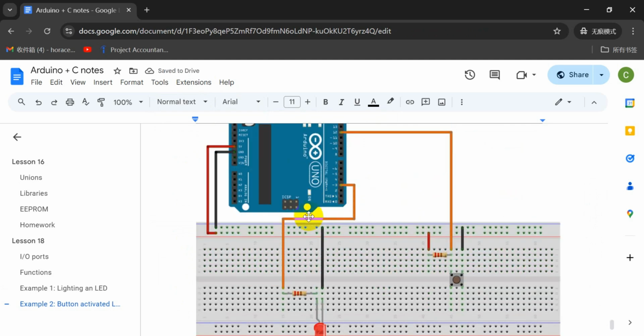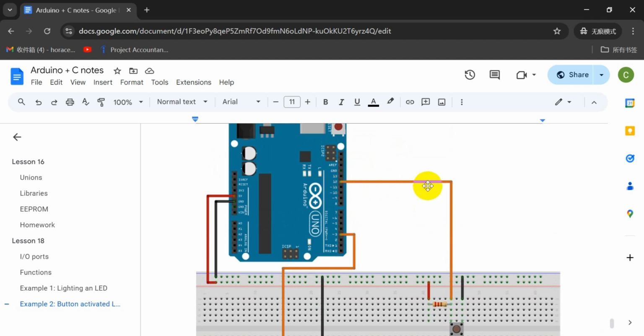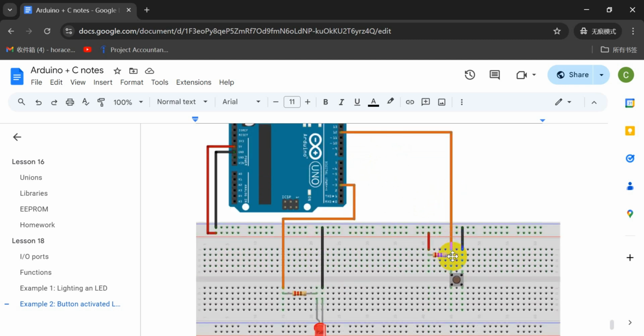This part is still the same. You still need something here and then a button here. Now the button just gives an input back, so we can determine whether this should be high or low. And here we use a very classical pull-up resistor type of diagram. So power comes in through number 12, and then if the button is not pressed, it goes through this resistor, comes here. Oh no, sorry, the power comes in through 5 volts. This is the input for the Arduino.